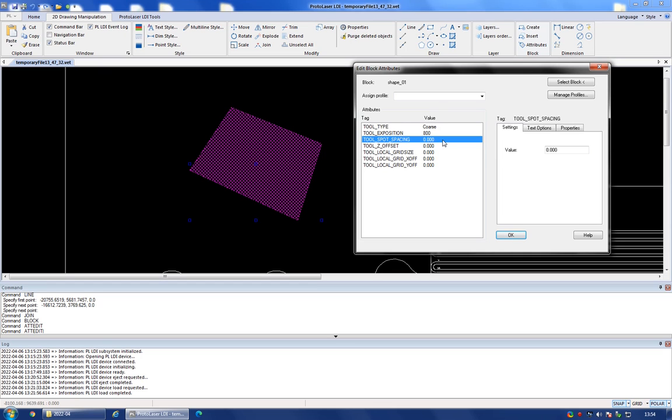And this spot spacing setting allows you to set an additional offset between the different dots which the laser writer uses to do the exposure. Then you have this setting about the Z offset. This is useful if you're having very, very thick films, say 50 micrometers or even more, and you can adjust the laser focal plane compared to the leveling procedure that we will do afterwards.